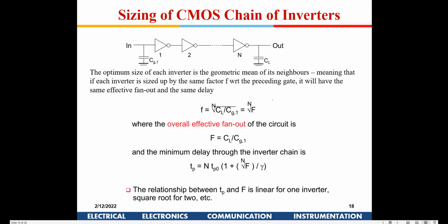One question over here. Basically over here we have n, the subsequent fan out. We are considering that n is creating another fan out port, but over here the stage 2 is already a fan out of stage 1. So there will be a C_L corresponding to stage 1. Can we consider that part in the propagation delay in this case? Yeah, we are going to consider that.